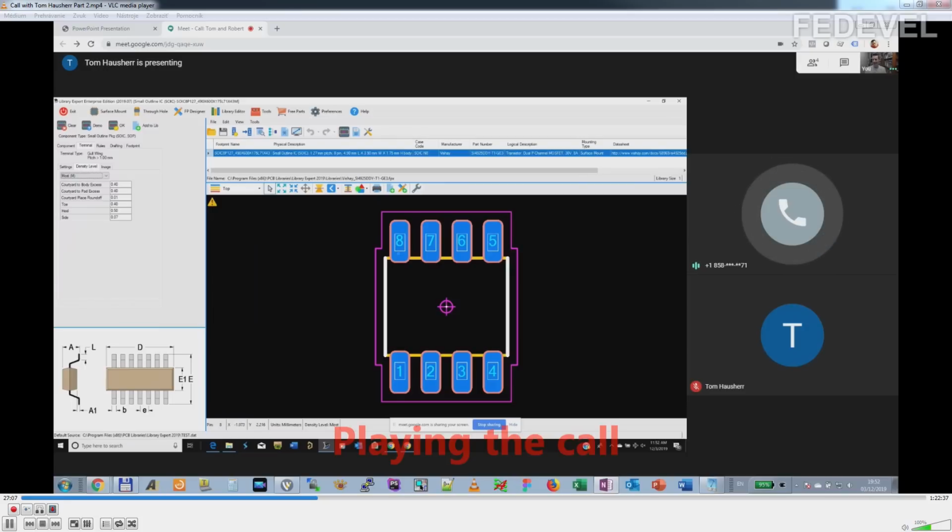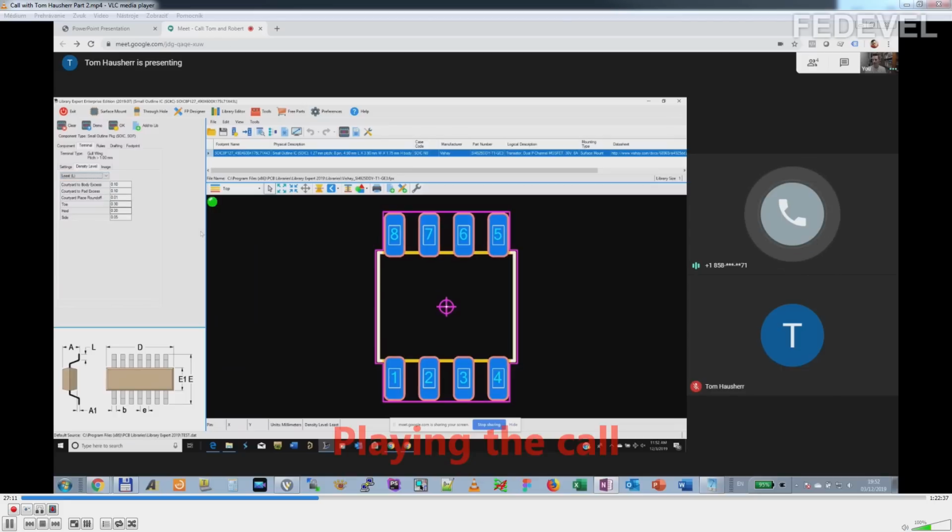Right. Okay, reliability. And then when you have your least land pattern, it has your smallest toe, your smallest heel, your smallest side, and your smallest courtyard, for packing densities. Now, this is for cellular phones or handheld devices. This is for the highest packing density. So you want to use the least amount of solder and the least amount of pad, so your pad size is very small. But you go into risk that they are not so durable, yeah?